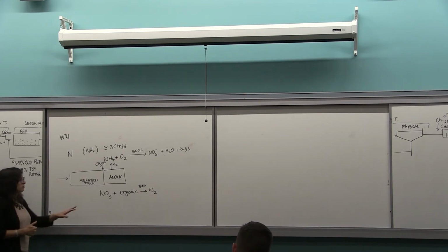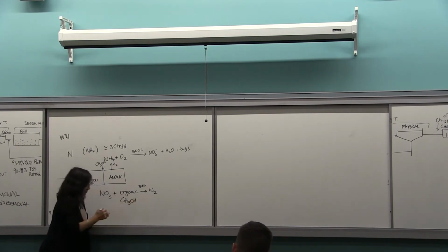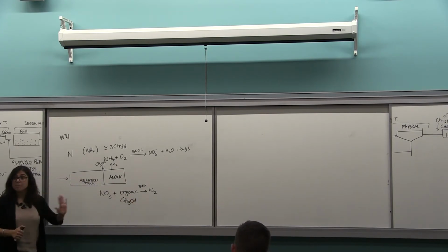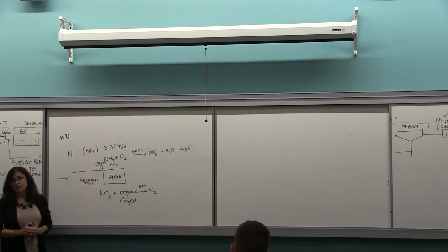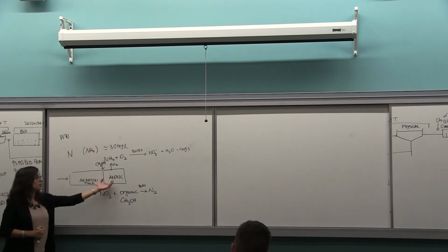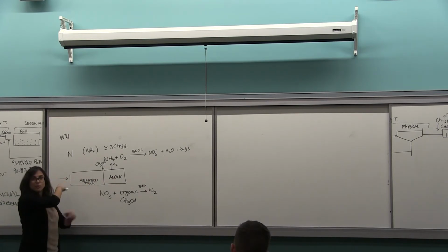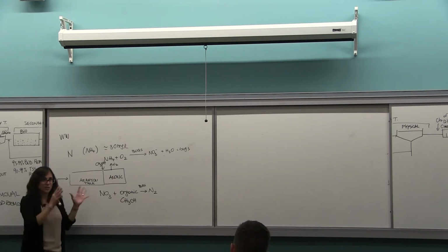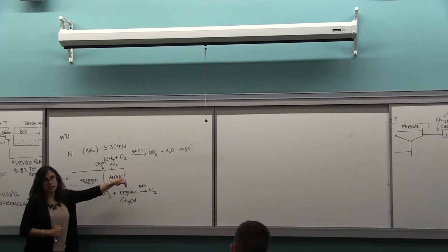Okay, and there are different schematics of this nitrification and denitrification, because if I put this before, I can use the organic, but I have to recycle because I don't have the nitrate. So there are different types of processes to do removal of nitrogen, but one simple one is I nitrify and then I denitrify.